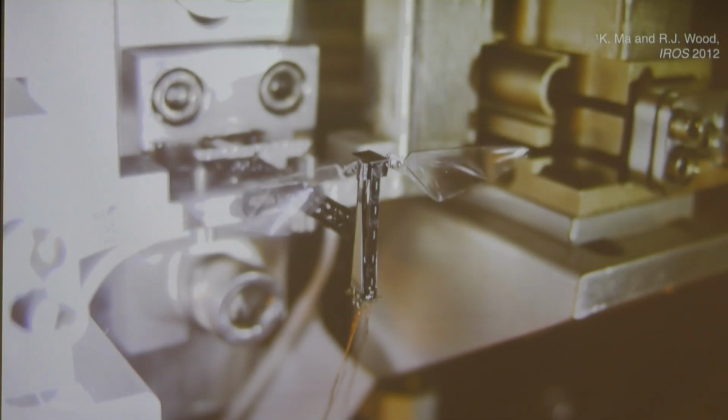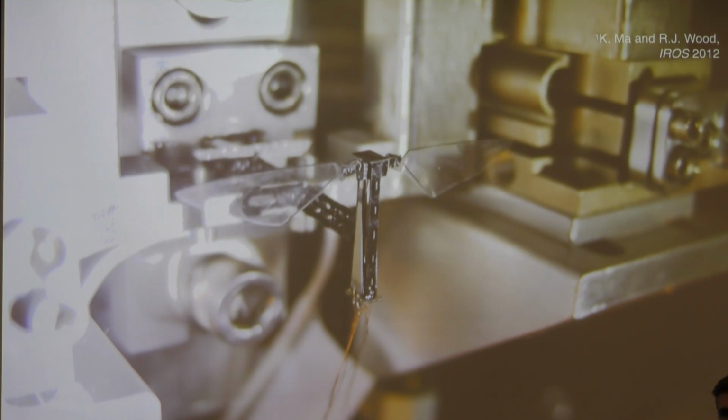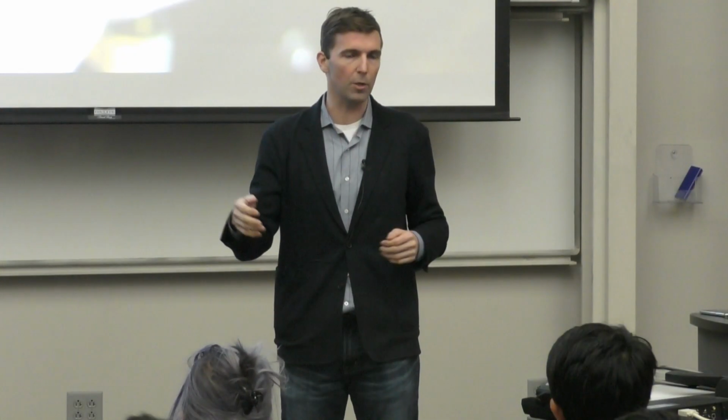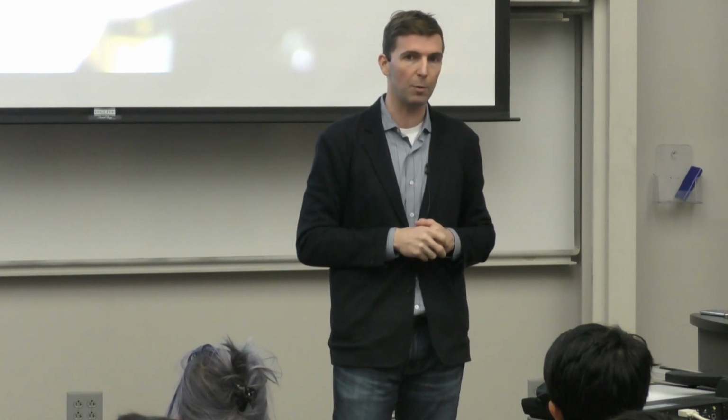But if we think about these 2 degrees of freedom, then that's what we need. As a sort of naive roboticist, the way that we started off thinking about this was, well, if I need 2 degrees of freedom, then I have 2 actuators, and I have some mapping, let's say, a differential mechanism that maps these 2 actuation motions into this desired flapping pattern.